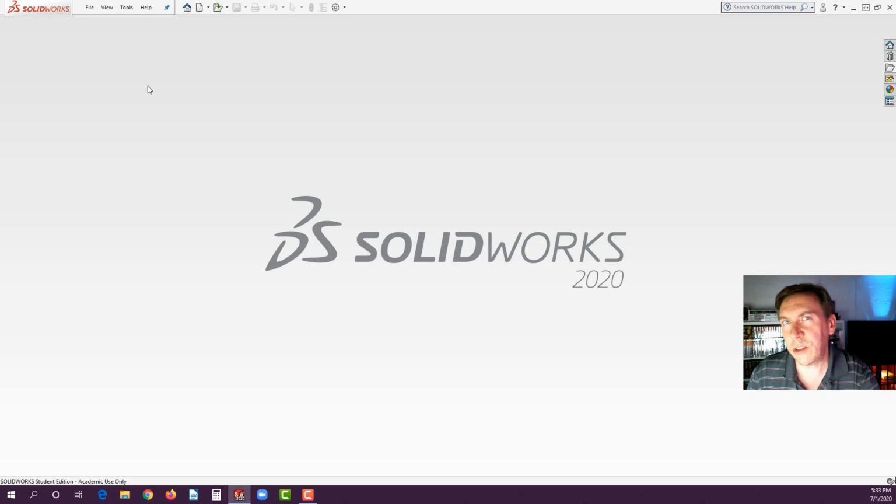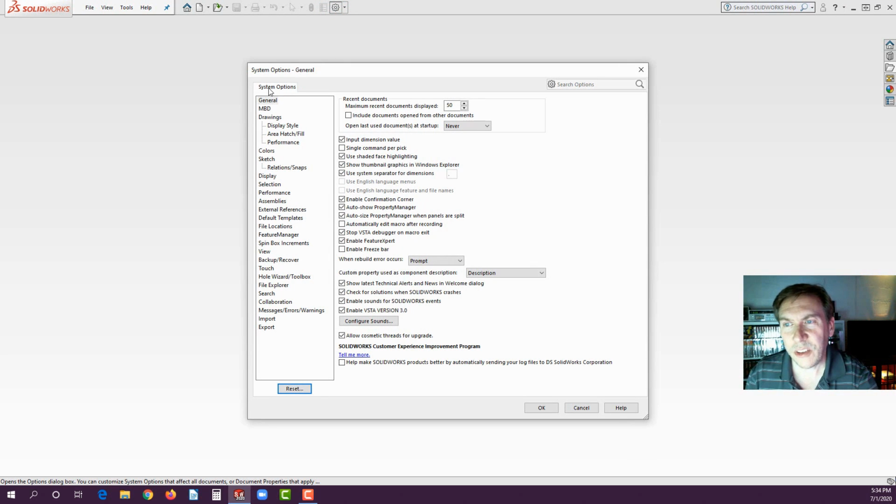Okay, your screen, if you just started it, might have prompted you for IPS or MMGS, millimeter gram second. Depending upon what region or country you're in, it might have defaulted to one or the other. You could select it. Just so you know, most of my exercises are in inches. So those of you in metric, you could do conversions or you could easily switch it. And the way you would switch it is right up here. There's that little gear in the options menu. And you'll see System Options.